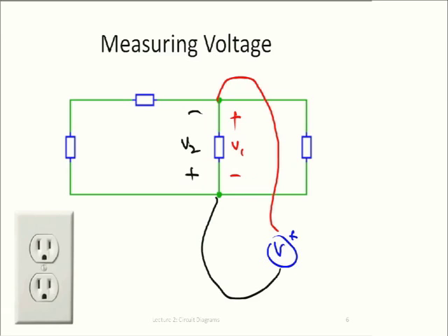Why is that? Well, you think about it. Is any current flowing through these wires? There shouldn't be current flowing through these wires. If the voltmeter was perfect, there wouldn't be any current flowing through these wires. It's not going to be perfect, so there's going to be a small current flowing, but hopefully it's so small that it doesn't matter. Well, if no current is flowing, then why should it break? Well, if the voltage is really high, 10,000 volts, it probably will break, and something will break down, right? Put a high enough voltage across the gap, what happens? The spark flies, right? And so that effect then will destroy it. It gets hot and burns up.